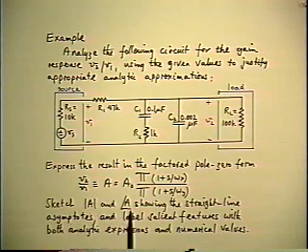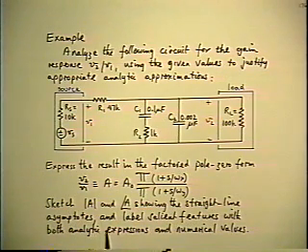Sketch magnitude and phase of the gain showing the straight line asymptotes. Label salient features. Salient features are the flat gains and the corner frequencies, with both the analytic expressions, which we now know, of course, ought to be in low entropy form, but they haven't heard that yet, and corresponding numerical values.